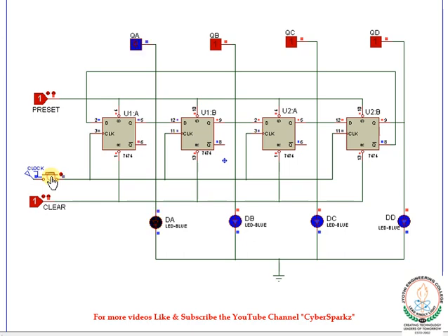So the next clock pulse, the output is 0111. On the next clock pulse, output is 0011. And the next clock pulse output is 0001, and the next clock pulse output is 0000. That is the initial state of the counter circuit.